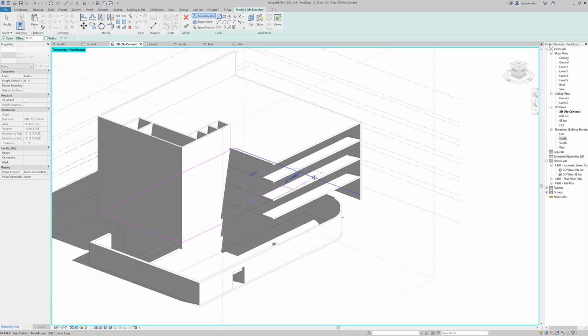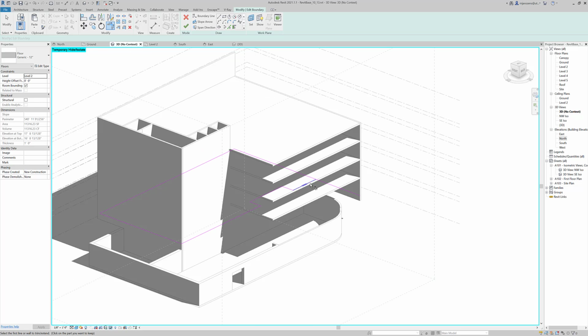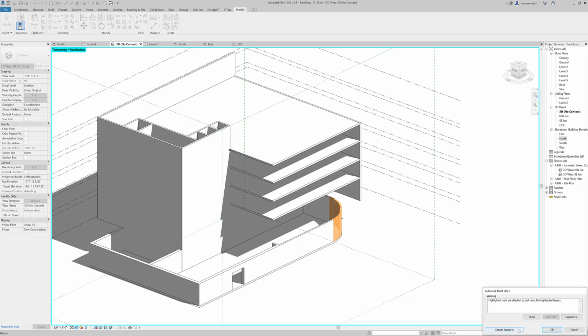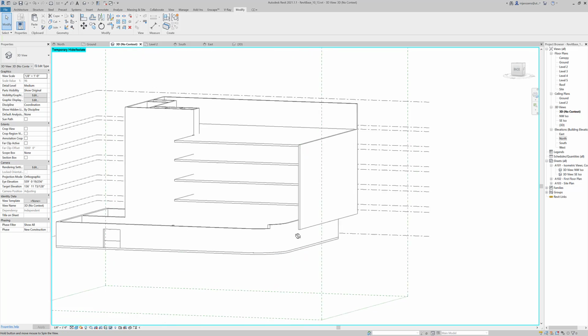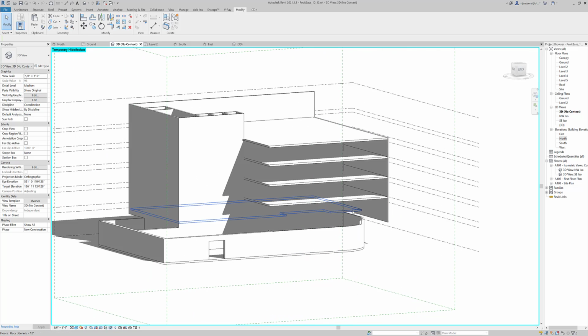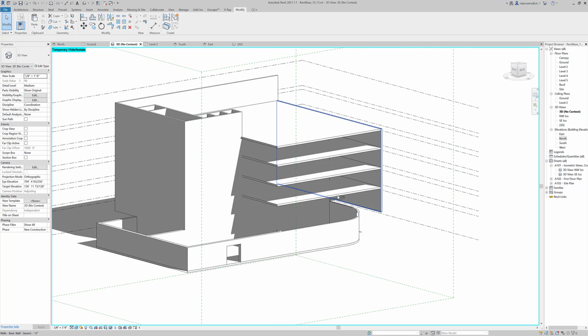And I'm drawing in 3D, which is not the greatest idea. You might want to go to the mode where the floor is drawn in if you're having a hard time seeing. But I'm going to fillet these elements together, and let's hit check, and that's okay. And so now you can see that one floor has been brought back, because I don't necessarily need that. I'll have a staircase that sort of wraps around and goes up in there.